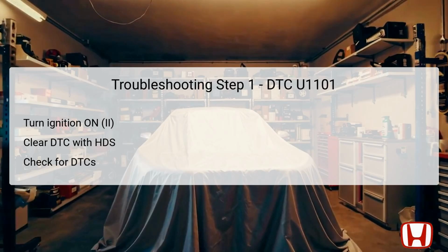Conversely, if no code is present, it suggests an intermittent failure, implying that the system is potentially functioning correctly at this moment. It is recommended then to inspect connections or terminals for any signs of looseness or damage.